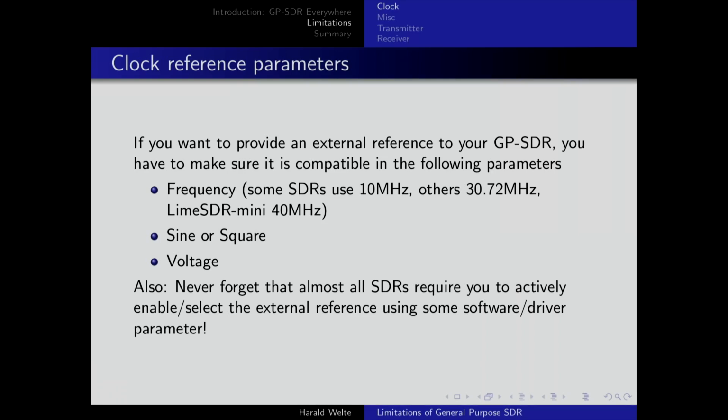I'm sure there are other reference frequencies that they want. And so you cannot just buy a single GPSDO that outputs a single frequency, but then you may need some other devices, some PLLs, that can actually generate the frequency that you need from the frequency that your GPSDO generates.